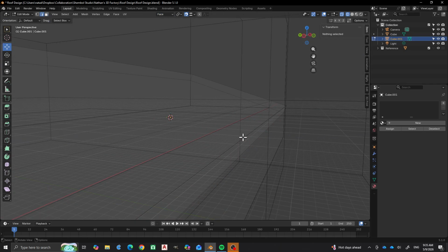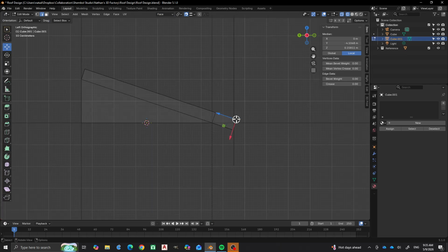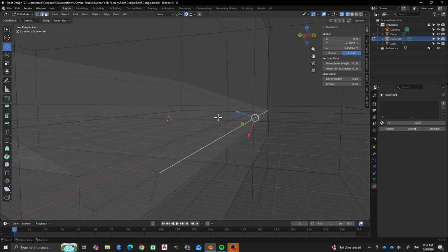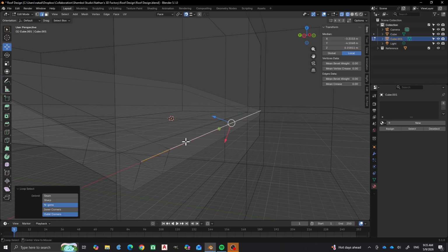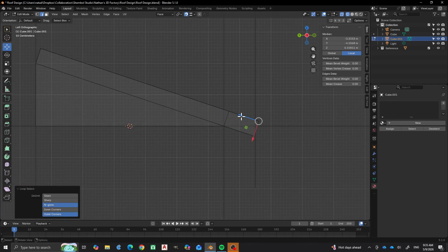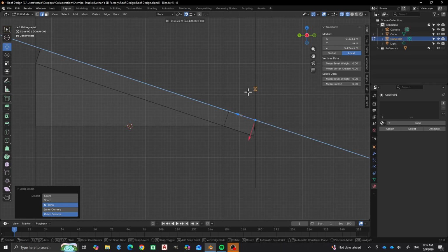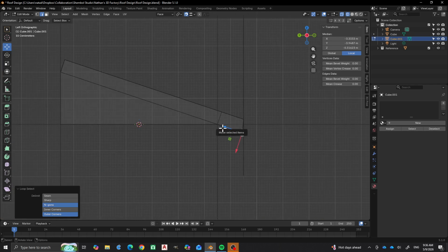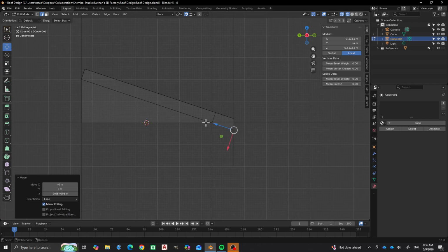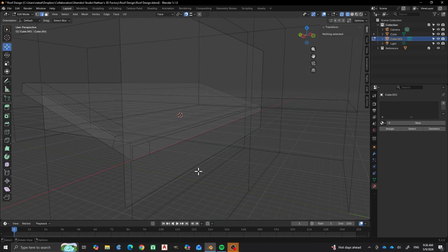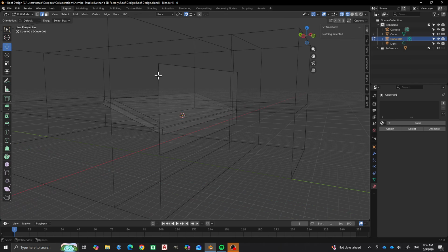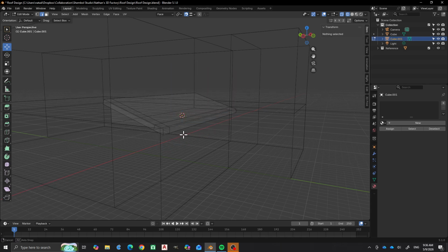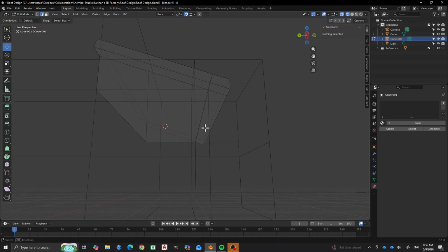Okay, so now if I go to 2, edge select, now we have that. Oh yeah, I probably ought to take this so the entire edge loop is selected there, right? Okay, so now I have this snapping to the edge. Really cool, right? Now let's do the same thing here. Okay, and then we're gonna do the same thing there. Pretty cool, isn't it? So now that we have that, we can press L, delete those vertices. Okay, so there we go on that.